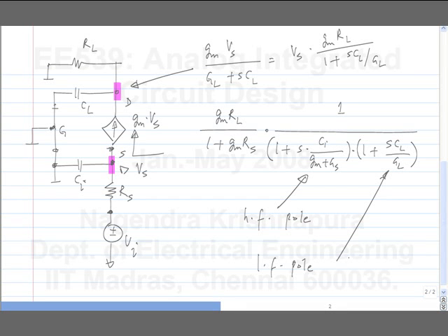What is the difference between this and the common source amplifier? What's an important difference that you see? The absence of a zero. Okay. And that turns out is a crucial difference because if you have a capacitive coupling between the input and output, you change something on the load side that influences the impedance on the source side. So it can give you problems when you have a number of amplifiers in cascade.